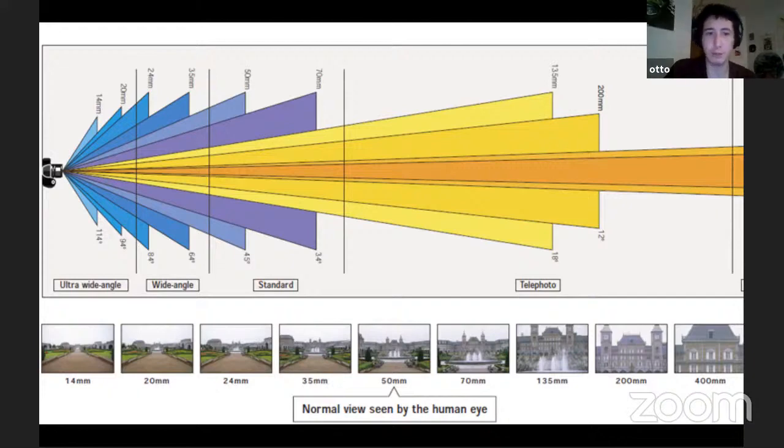Each focal length can have different uses. We often use wide-angle lenses for more architectural photogrammetry, and longer lenses for getting very specific details of buildings. But by and large, we try and stick to 50mm lenses if we can, which are a happy medium where the lens carries minimal distortions.